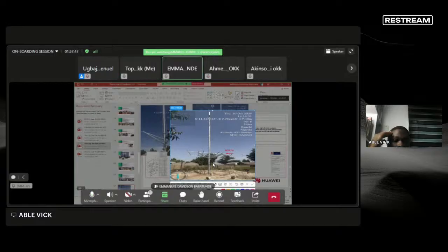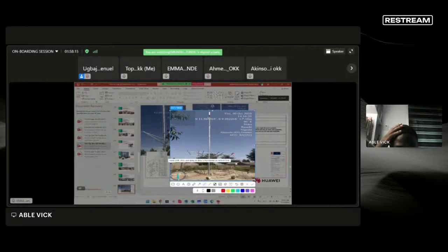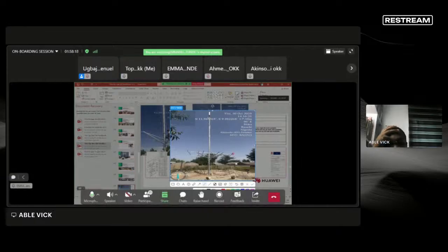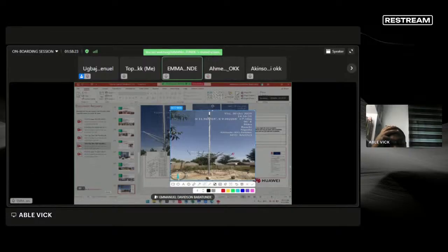No, this direction is not for the tilting of your panel. This direction is to make sure the sub-rails are not installed at the edge of the beam. If it does not face north, this last sub-rail will be installed at the edge here. If you let it face south, like this, you'll have something like this. It will be installed at the edge, which is not safe.